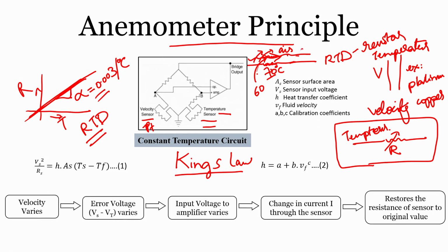And if you drive the fluid at even higher speeds from what it is in case A and you increase it to a higher velocity, that is A square. So, when the velocity increases, again because of the increase in convection, the temperature might drop as low as 40. These are not the exact numbers, but I am just telling you how they are related to the fluid flow, with the increase in velocity, how the temperature drops. Now, with an increased fluid flow, the temperature is dropping.